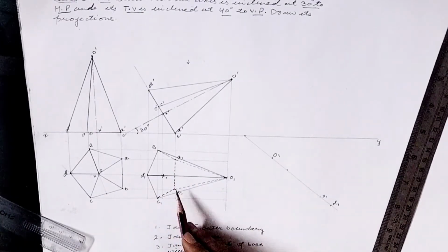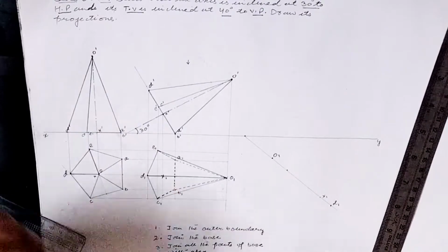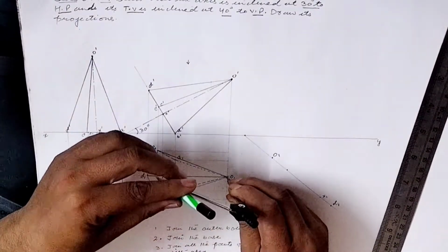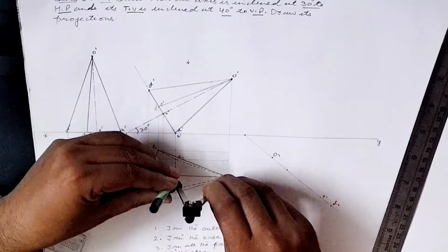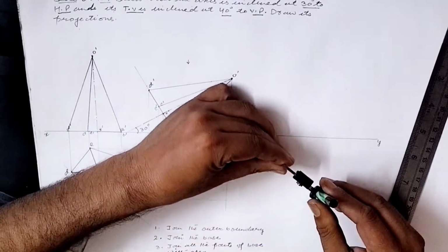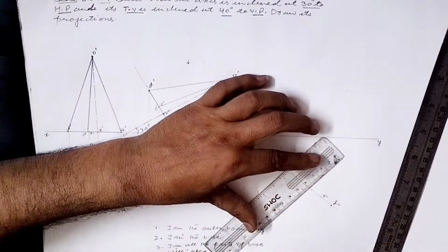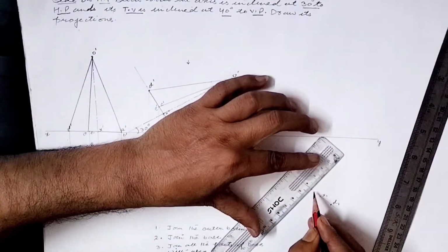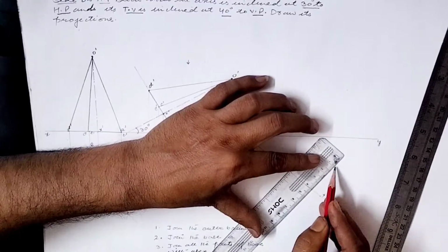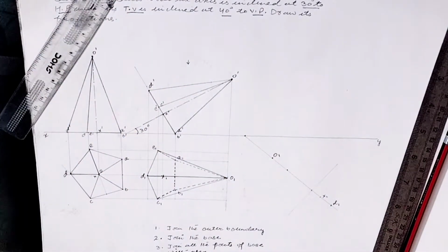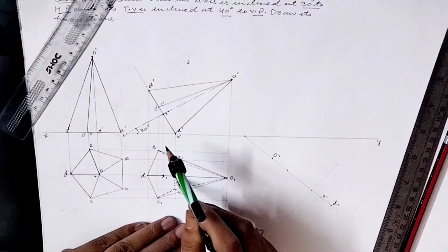We can see O1, cross 1 and D1 are in the same straight line. Then mark A1 and B1, which are perpendicular to O1 and cross 1. While transferring the figure in the third stage, we have to take the help of a drafter. If we use the drafter, then we will get a more accurate solution.